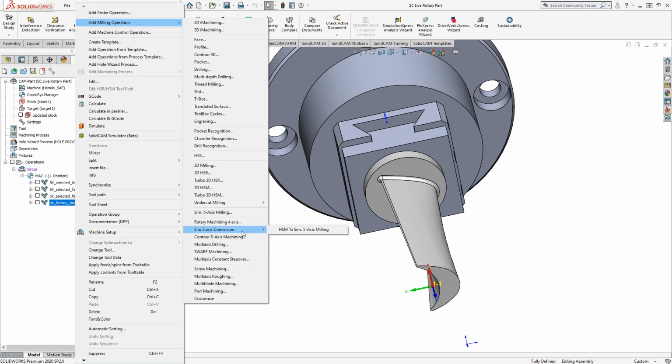So it's really just applying to HSM, exactly like Kevin said. Tilts the tool because of the fact that you might not have enough reach. The contour 5-axis machining is the idea that maybe you don't have surfaces either already on the part or surfaces at all that will tell you where to move your tool. Because remember, with the simultaneous 5-axis toolpath, you're choosing a surface to dictate the travel of the tool, where you'd like it to go, and in some instances, how to angle the tool.